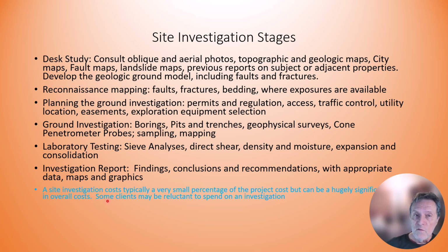So, look here, site investigation is critical. I've had some clients in the past that try to cheap out, try to cut corners on a site investigation, not realizing that $5,000, $10,000, $20,000 spent on a site investigation are well worth the dollar cost for a project that's going to cost them $2 million, $3 million, $4 million. If a site investigation is done incompletely, not thoroughly, and something is missed, that may well result in increased site preparation and construction costs, which you don't want to stick your client with. So you try to do as complete an investigation as possible.